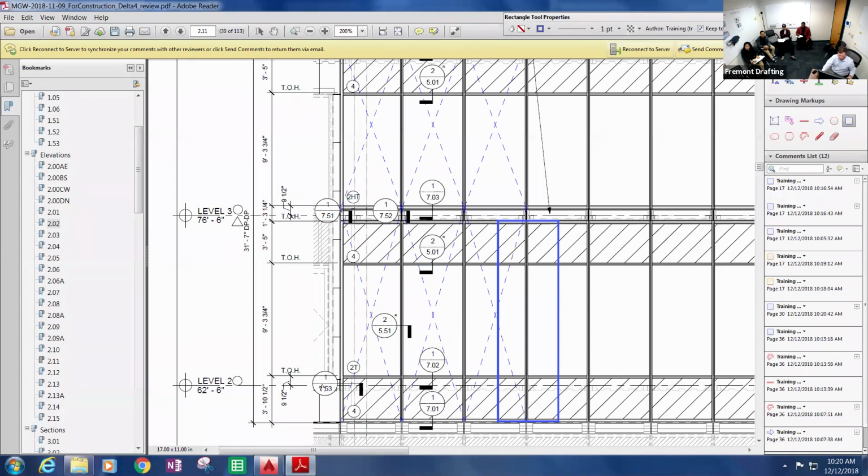And so then this anchor, I have an anchor at the floor line here, and I have an anchor up here, and then there's a cantilever down here as well. And so there's a deflection criteria for cantilevers as well. It's typically 2L over 175, so twice the length divided by 175. And that length here is the length that cantilevers past the anchor.